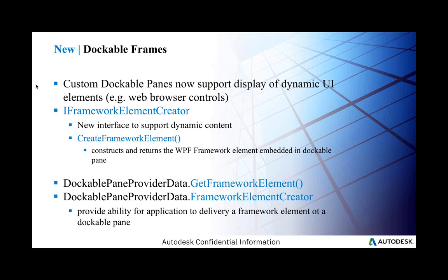There's a new interface on the dockable panes to support dynamic content, and a method CreateFrameworkElement to construct and return a WPF framework element embedded within the dockable panel. The dockable pane provider data, get framework element and framework element creator provide the ability for applications to deliver a framework element on a dockable panel.